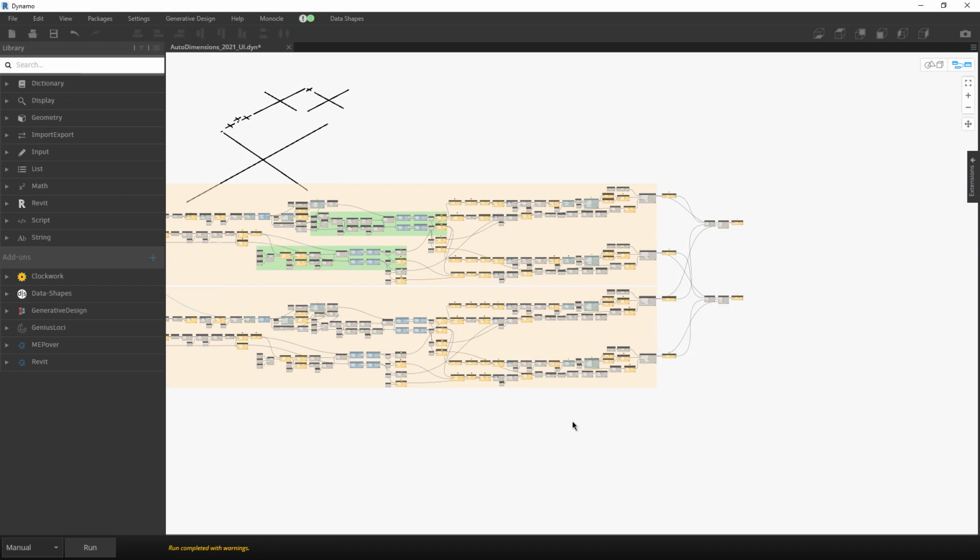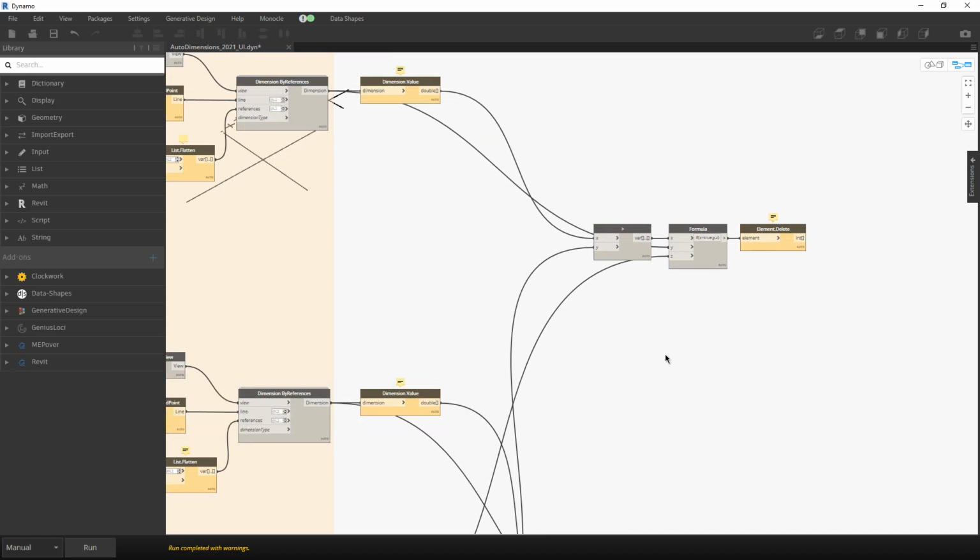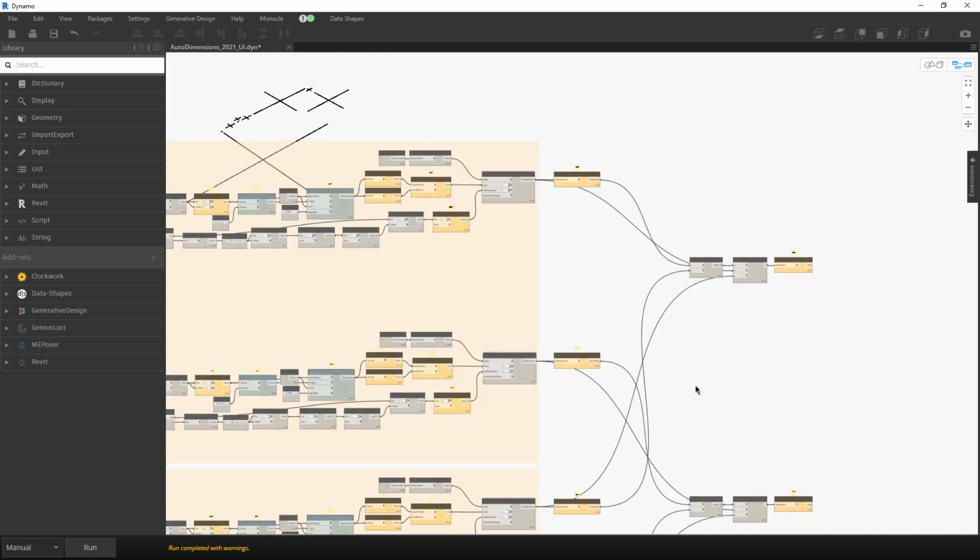So at the end, I will basically create two sets of dimensions. If I have 150 ducts in some view, I will create 300 dimensions, and then I will see what is the value of those dimensions. Over here everything is yellow because we chose to go with cable trays and grids, so I sent a false message to this entire part of the script in order to execute it faster.